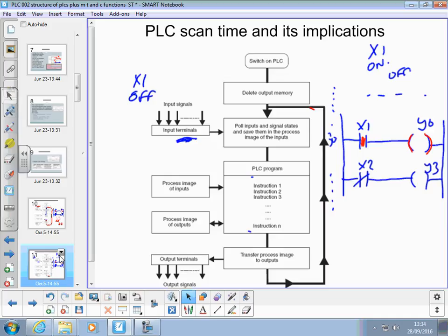All right. So that's a little bit of an overview of, and sometimes you'll hear this called mass I/O copying, because what you do is take a mass copy of the inputs, deal with them, and then en masse copy them to the outputs at the end, and then refresh and keep going round and round and round that all day long. Very fast. Okay, everyone happy with that?